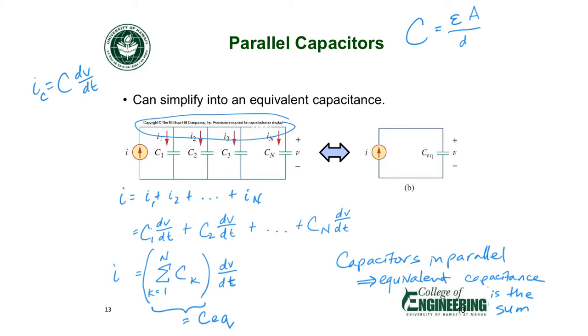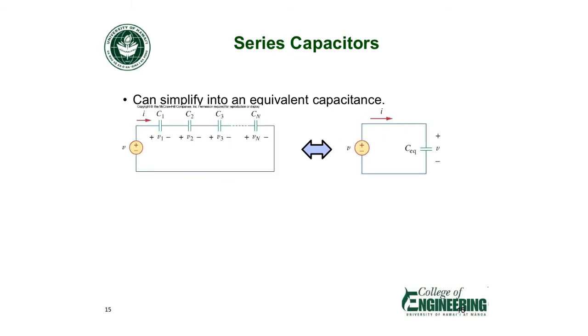The only confusing thing about this is that if you had resistors in parallel, right, you're not summing them up. You're doing a summation of the reciprocals and taking the reciprocal of that. So when you put resistors in parallel, the equivalent resistance goes down. Okay, for series capacitors, this is going to be like resistors in parallel.